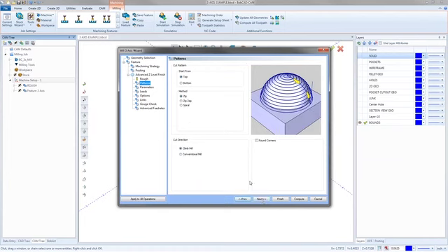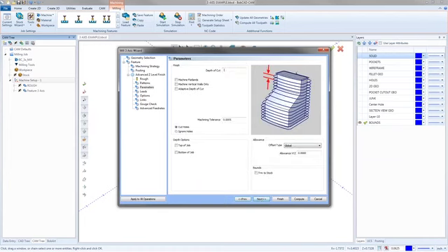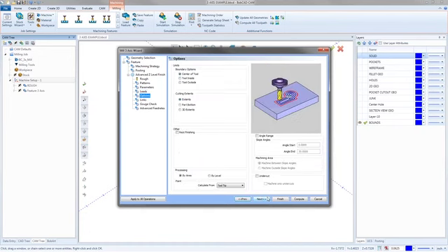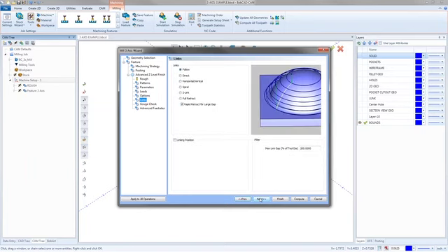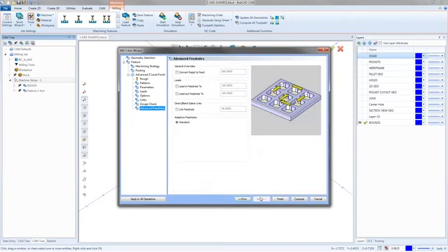So for this one, we're going to go from the top down. I'm going to do a depth of cut on this. We'll go 20 just so we get a bit nicer finish on it. Other than that, just work my way through 3D extents. No angle range on this one. And then no changes for the links, no changes for the gouge check, no changes for the advanced feed rates. When you go through these toolpaths, it shouldn't take you but a couple minutes to get through each one. 2 minutes per one.